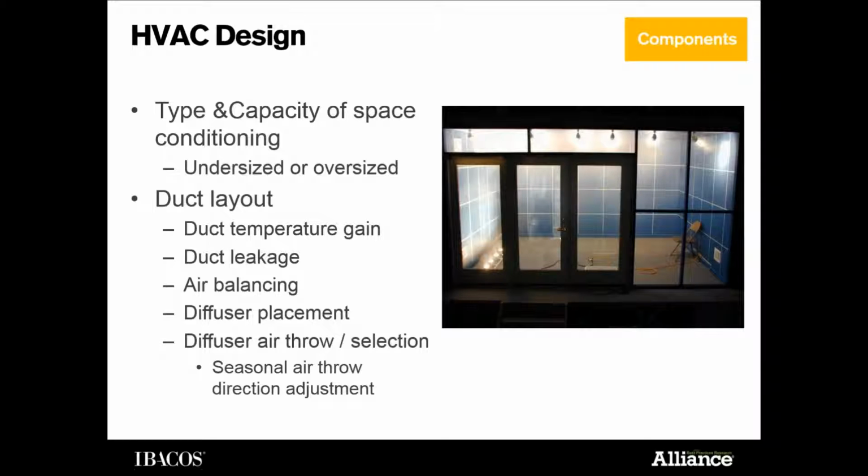Duct layout. With both of these, we want to make sure that this whole system, ducts and space conditioning, is in conditioned space. When you start having this equipment outside of conditioned space, it brings up a lot of other issues. Separate from comfort, it brings up issues with regards to energy. So on the duct layout, we're looking at duct temperature gain and duct leakage, which has been common in the HERS industry for a long time.